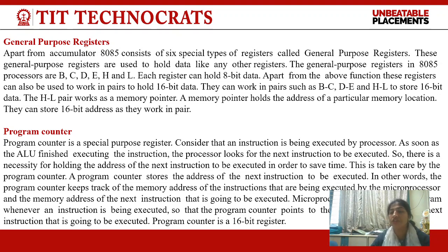The processor increments the program counter whenever an instruction is to be executed, so that the program counter points to the memory address of the next instruction that is going to be executed. The program counter is a 16-bit register.